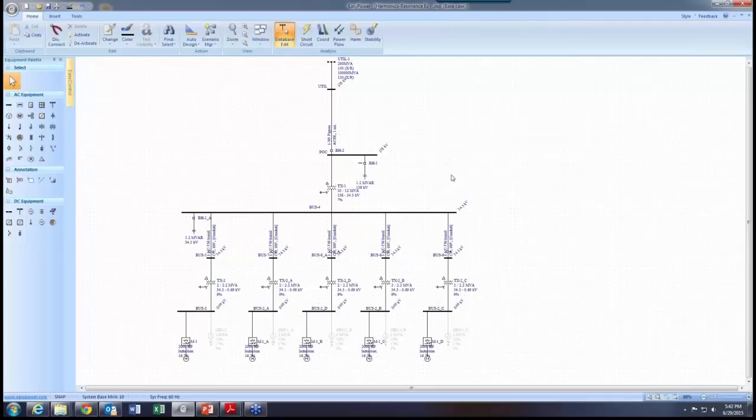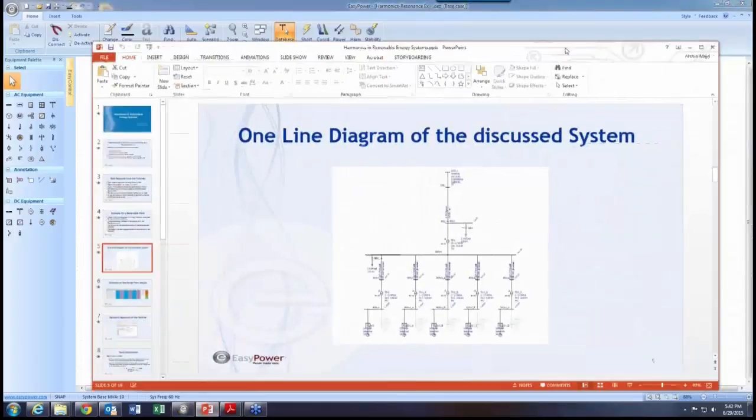Those of you who come from the wind industry would know that this is representing the collector system, where the entire turbines and plant, the currents and all the power, are coming here. We collect them here, pass them through a high step-up transformer, and send them to the utility. That becomes the point of interconnection to the utility, which is here. This example is 138 kV. Now, we calculated this value before, so I have this cap bank here.